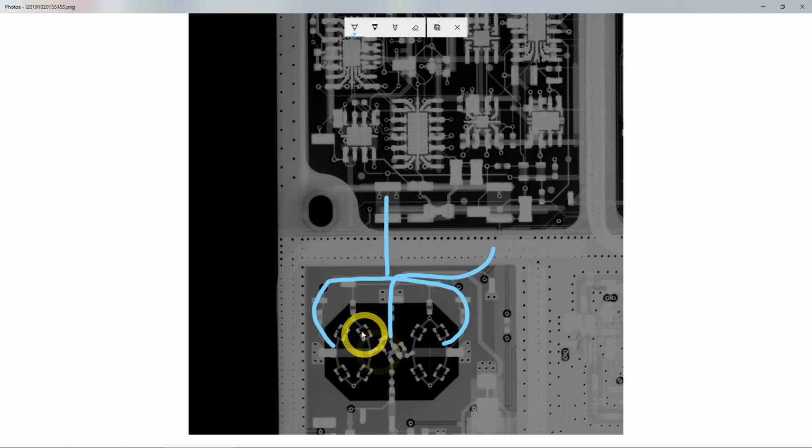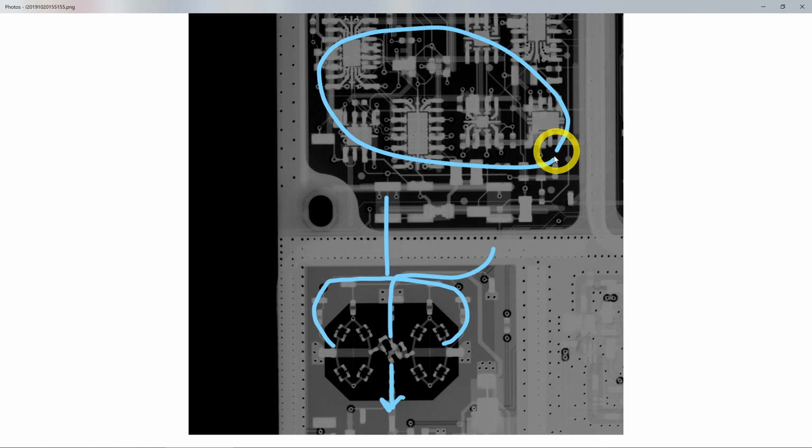There it is, the pre-tune and the FM tune. That's what controls the VCO, and you can see they're isolated by the inductors, which are AC blocks, and they allow the oscillator to oscillate internally and be completely separated from the signals coming in. This is a normal technique, of course. This is even done in integrated circuits. So going down here is the output of the VCO. All the way up here is all the analog circuits that control the VCO.